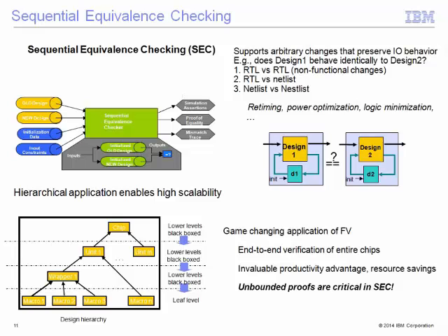As you said, when we are reaching the later stages of the design cycle, we check at the macro level, then we perform the SEC, then we do black boxing and reach a higher level slowly. We have a big saying that formal is applicable only at unit level, only at macro level. I think we have gone far due to the improvements in the algorithms and advancements in the tools. Now we are able to do it mostly at the block level and the macro level, but we are also moving to some extent to higher levels with semi-formal as well as black boxing and hierarchical approaches.